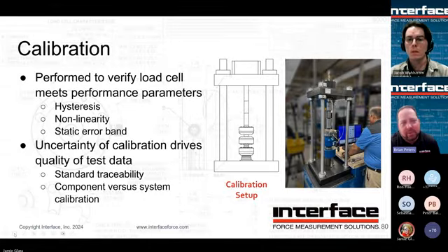So just for reference, if it's an LP we're talking about, most of our thermal compensation is going to be done for the zero balance, at least behind our label. So pay attention to that. You don't want to have anything hot shooting right at our label. That's not going to allow the thermal comp to work as best as it can. So Jake, were you going to say something? No, just great question. Yeah.